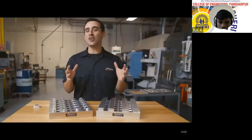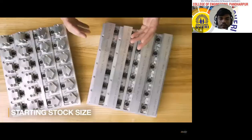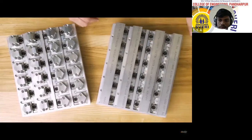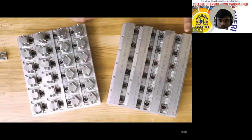Okay, enough math. Let's take a look at the design details. The first thing you'll notice is the starting stock size. We've minimized our need to saw individual part blanks and opted to machine them in strips that yield 6 parts per blank. At the end, we simply slot them apart into individual pieces at the end of the cycle.